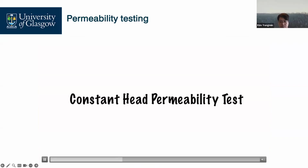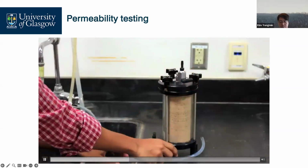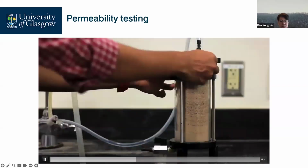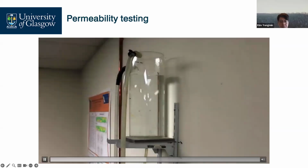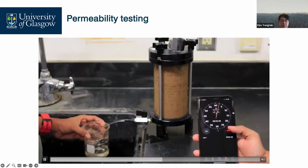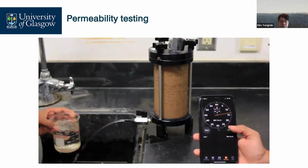Constant head permeability test. Make sure the top and bottom valves are closed. Connect the pipe with the apparatus. Open both the valves, and the soil will start to get saturated. Make sure that the water head remains constant. Allow adequate time for the flow pattern to stabilize. Measure the time it takes to fill a certain volume using a graduated cylinder. Measure the temperature of water. Repeat the process 3 times. Compute the average time, average volume, and average temperature.